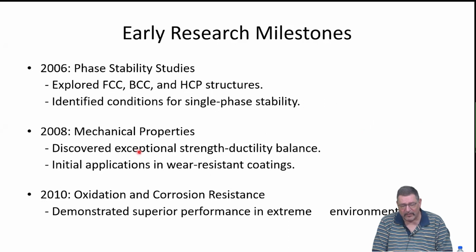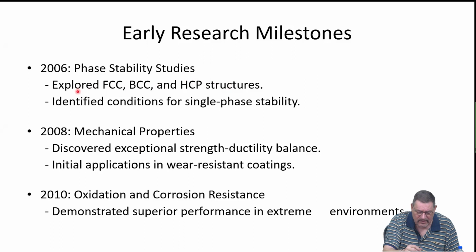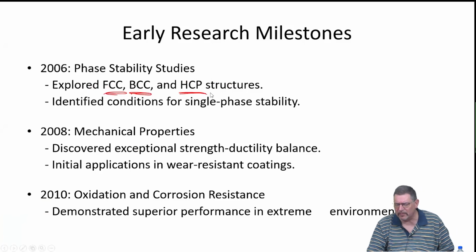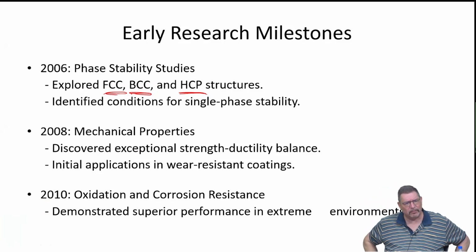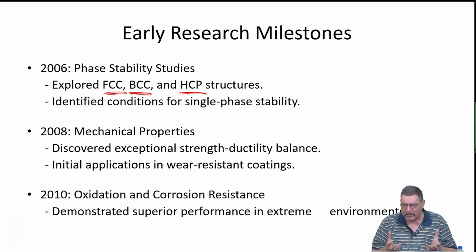Obviously, in later stages people were making high entropy alloys already, and I think it's important to say that even early on people found not only FCC but also BCC and HCP structures. We will talk much later in the course also a little bit about intermetallic phases which have high entropy features, meaning that they have a more complex structure but still consist of 5 elements.